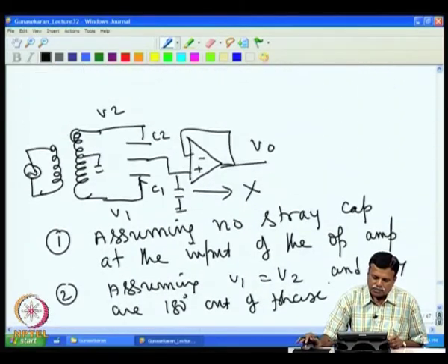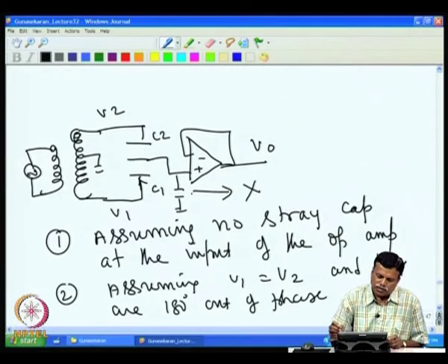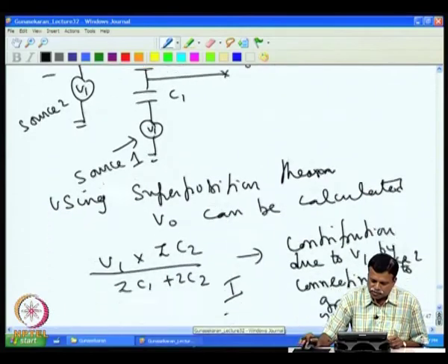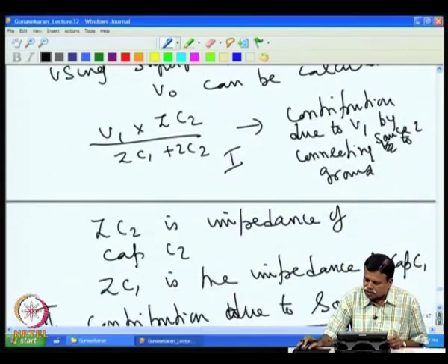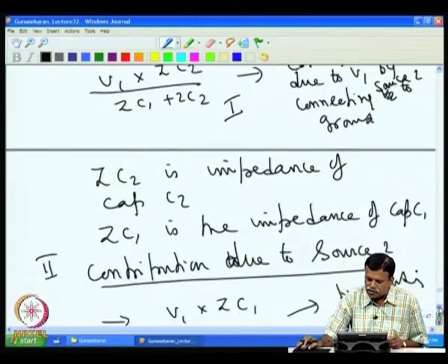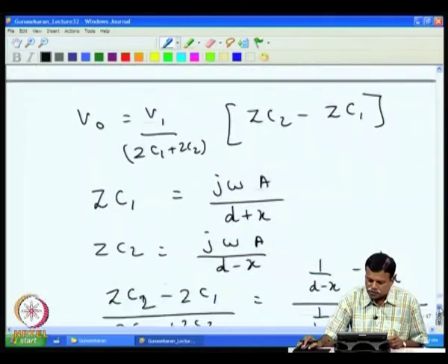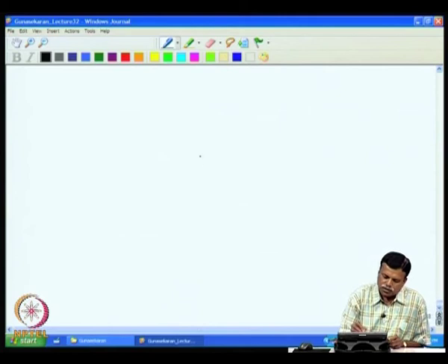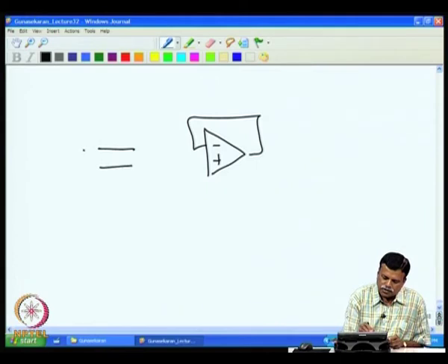Now, the dependence on this capacitance can be solved by guarding the input. Normally, to solve the input stray capacitance problem, one can guard the input electrodes. So, using the following technique, we can have the input and then the two space variation.